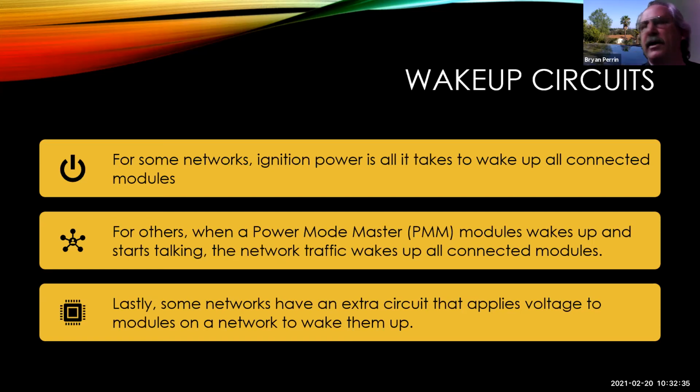So that's normally our master module. Lastly, some networks have an extra circuit that applies voltage to the modules in the network to wake them up. So this is a parallel circuit to the network that's sending out a voltage impulse saying, hey, time to go to work, you're getting traffic. Well, who's telling this parallel circuit to apply voltage? It's going to be a master module.